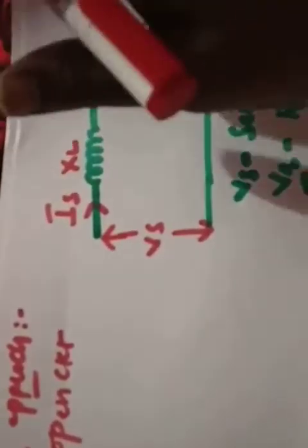Right? So XL and XC are the transmission line parameters. Right? So now we'll start. We know that the load is open circuited. Here you will see your load is open circuited. Open circuit means the current IR is equal to 0. There is no current from this side to that side, right? Because it's open circuited. What about IR? IR is equal to 0.